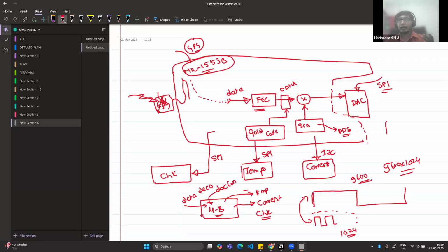You had external DSPs, like Texas Instruments DSPs, such as Sitara and some TMS series. Those DSP processors they used to put, along with a low-end FPGA like Spartan, and they used to interface using a high speed SerDes lane.